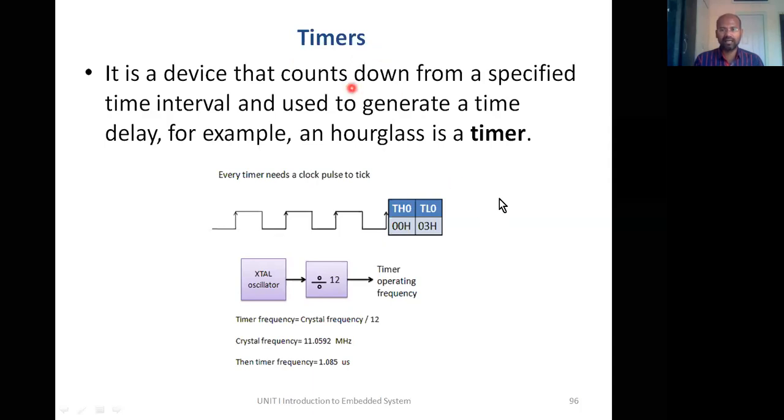A timer is hardware which is present in the microcontroller, right? It receives the clock signal from the clock generation unit, and it counts those clock pulses. Let's say the frequency of the incoming clock is 1 megahertz. What is the duration of one time period, one unit of signal here? 1 microsecond. So that counting circuit counts those incoming clock pulses, and the results are updated in the registers.